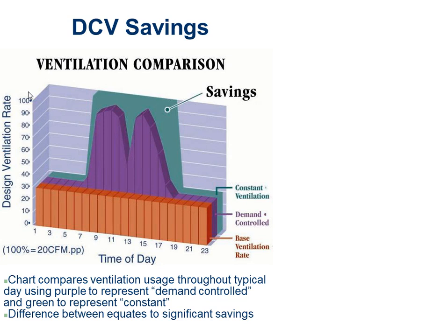This is 0 to 100% of the design outdoor air CFM. So in a normal building, we would ventilate to the 100% of the design. So we're moving along, 7 a.m. comes, boom, we turn on the ventilation system. I go to 100%, that's where I sit all day long. Then 5, 6 p.m. comes, I shut it off, boom. So that green area is basically my normal ventilation that I'm doing.